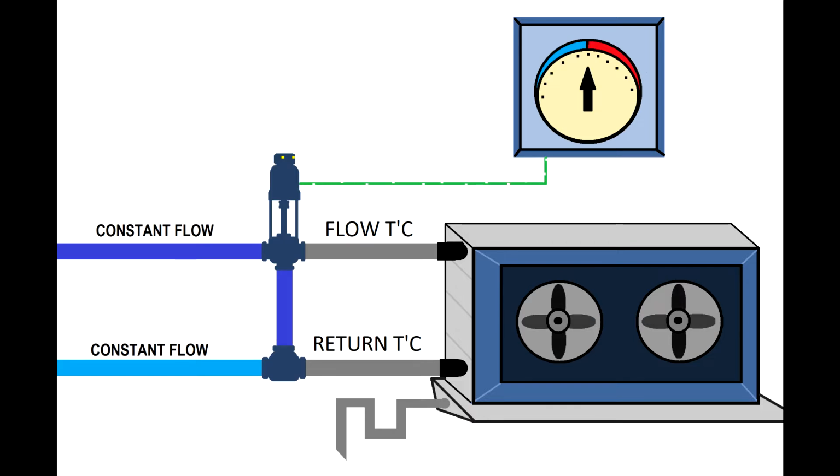When the heat exchangers run very cold, we have the possibility to eliminate moisture from the air, because the moisture from the air will condense onto the heat exchanger, fall on the drip tray, and be eliminated via the drip tray through the drain.